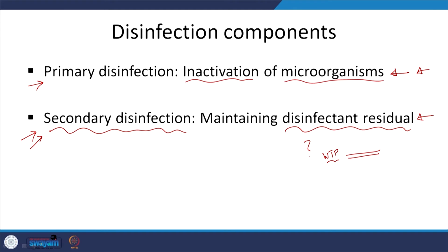So, in the context of the water treatment plant, this is not the sewage treatment plant, the water will have to be pumped over long distances to different locations, let us say. So, you can have microbial growth again, though you apply some chlorine here to kill the microbes, because of this long contact, long traveling time.